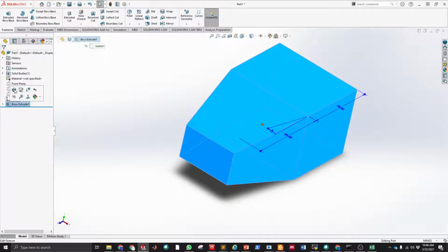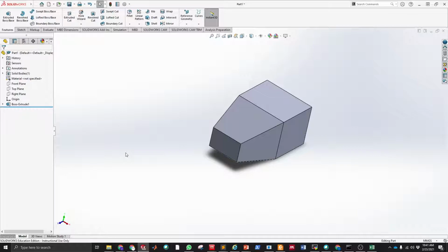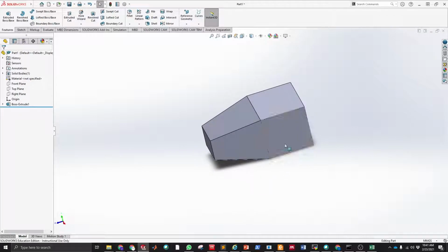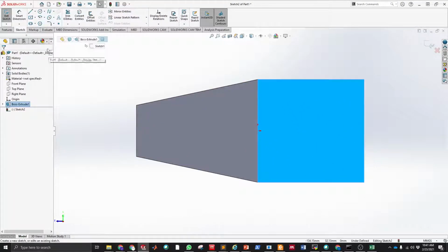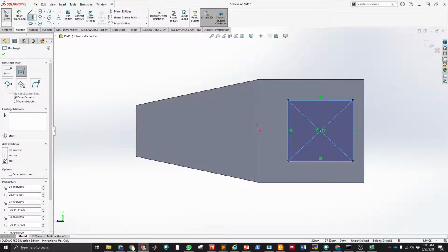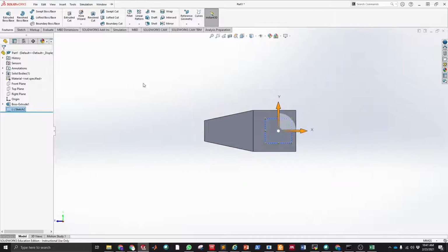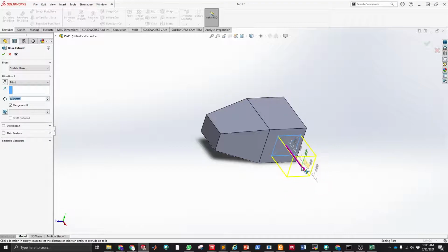And also, when you're doing these extrusions, you can also create thin features. So for example, I'm gonna create a new sketch, maybe another square like that. And then I'm gonna exit this sketch and create an extrusion from that sketch. But in this case, I'm gonna activate this button here that says thin feature.